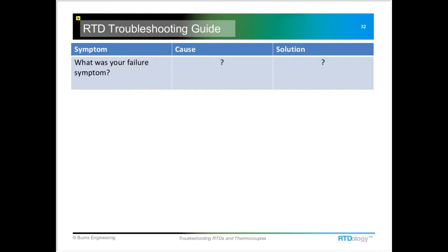There are so many things that can come into play here. Even a bad grounding system in the building. If it's a really old building, I've seen where there are more grounding issues, where stray voltage is getting into their grounding system, and that can cause a thermocouple to read poorly, to jump up and down like that.